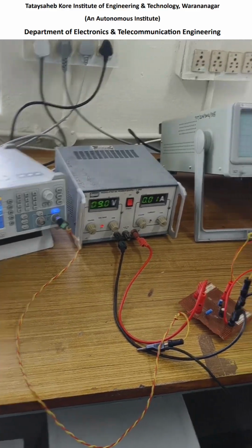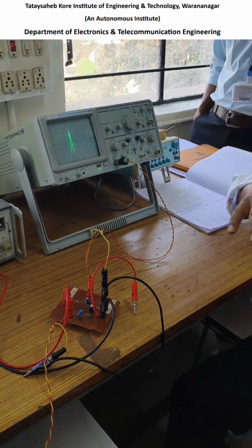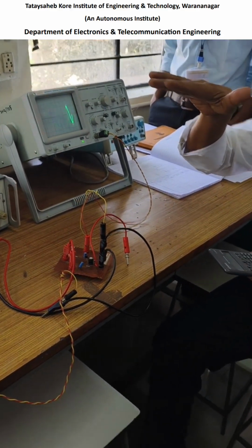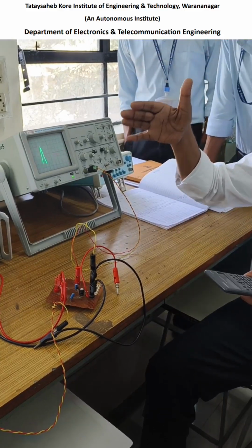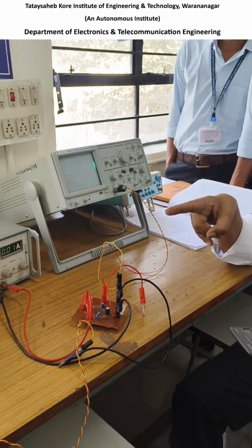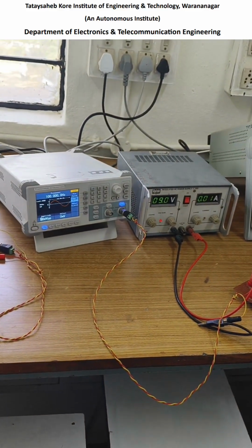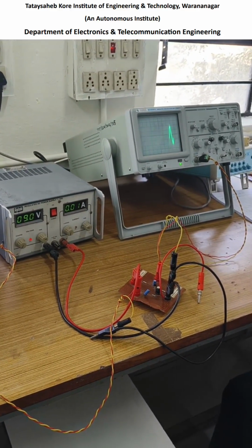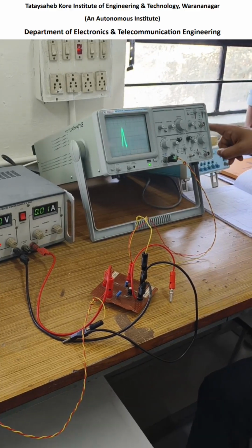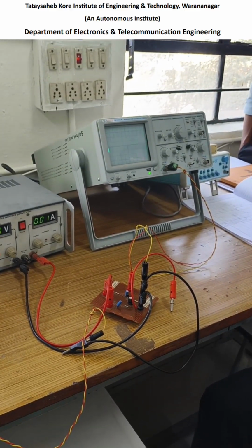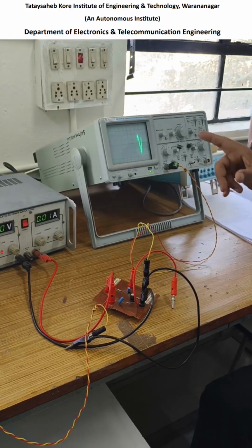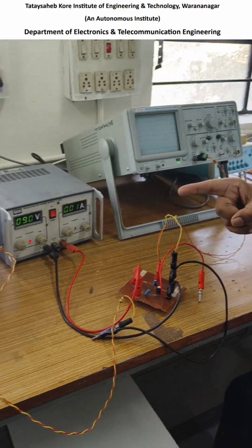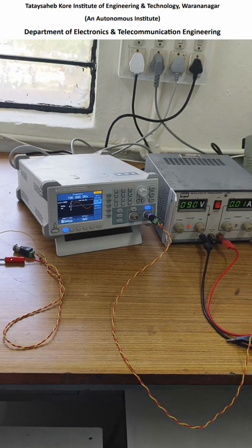This is one example I have shown. Now you will get that initially the output voltage will start increasing. In between it may remain constant and again it will start decreasing. So if you change the frequency from 50 Hertz to 1.5 megahertz, you will get the wave shape: initial rise, steady and then again fall. So that graph you have to plot on the graph paper, which will give you the bandwidth of your amplifier. So just as an example, I have shown the value for 100 Hertz. In between readings, I will show you.